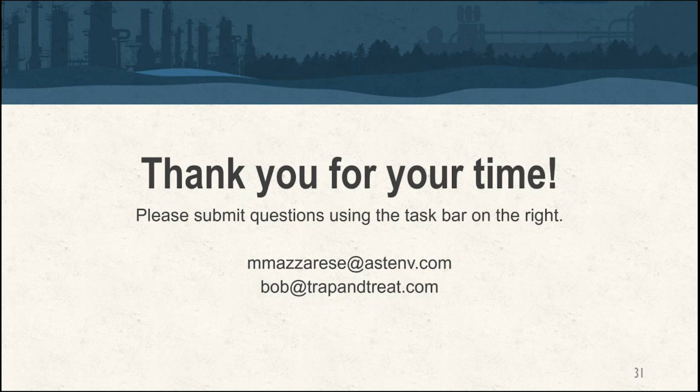We've got to account for all the mass, and it's got to be speciated too, so that's the point. We've got to know, for example, how much benzene is in groundwater, how much is in soil, but then also how much TPH mass is in groundwater versus how much is in soil. Because when we run our designs, we're looking at the speciated compounds, but we're also looking at the overall TPH mass to see what's going to be the limiting factor.